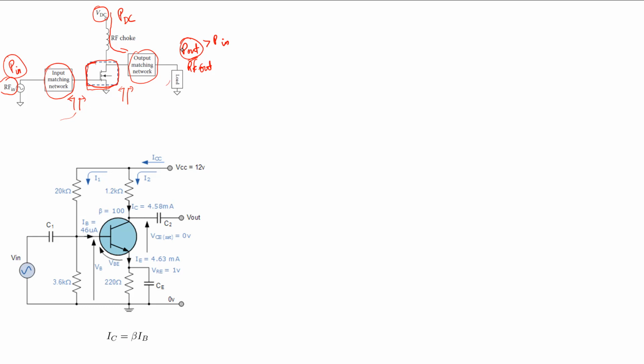So to understand roughly the consequences of using a transistor in an amplifier, the best configuration to take a look at is the common emitter configuration of a transistor as an amplifier. You know that a BJT, a bipolar junction transistor, is a three-terminal device with a base, an emitter and a collector. The device can be used as a current amplifier, with the collector current being a factor times the base current, and typically the current gain beta is in the order of 100.